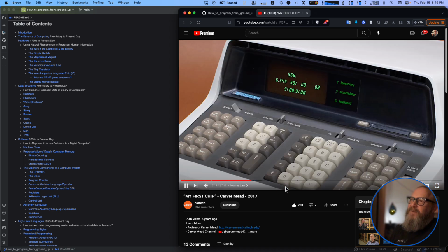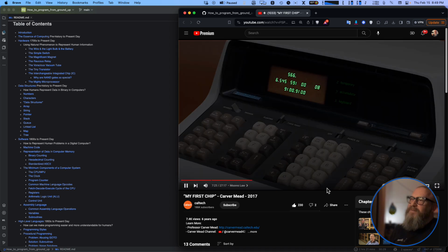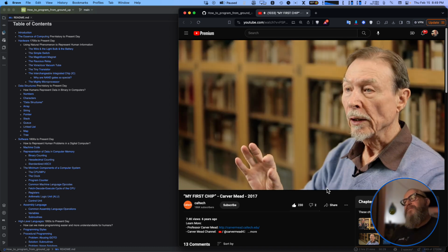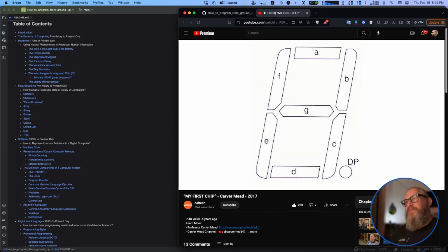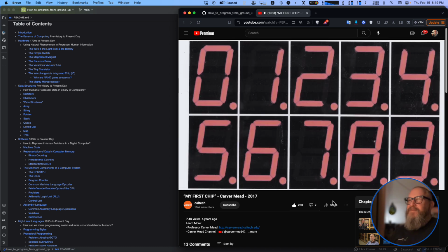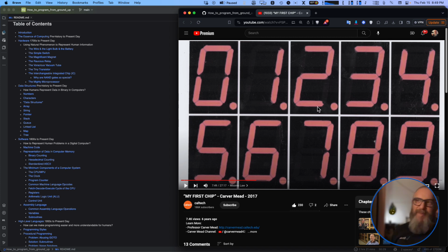You have to be able to get data out. You can see the display it has. Each position where there can be a number, there's a little thing called a 7-segment display. Each of these segments can be lit up independently. Here's A, B, C, D, E, F, and then G is in the middle. These segments can be lit up to make all the digits. They don't consider this one a segment, but it is a pin. It'll be the 8th pin, but there's 7 segments, and the 8th is the decimal point. That's very convenient how that worked out.